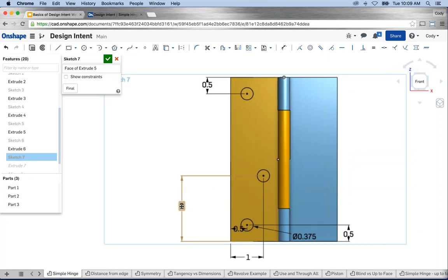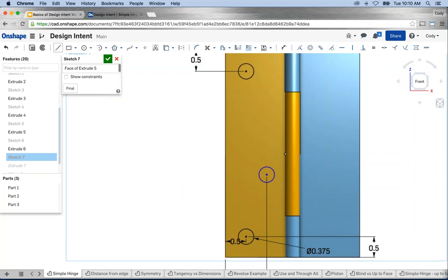As I mentioned before, this 2-inch dimension was centered, but it's not anymore because I've changed the height. So what I can do here is delete the dimension, and instead of driving it with a dimension, use construction geometry. In this case, a construction line. I'll select line, construction, move my cursor along the edge of the part, and you'll see the midpoint wake up. You'll see it just as I move the cursor right there. I've now hit the midpoint of that edge.